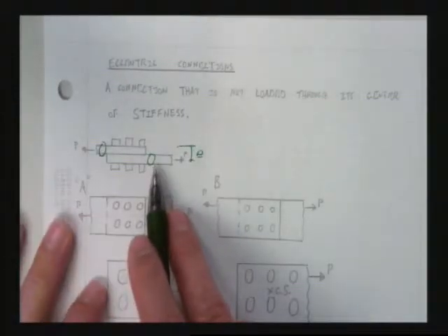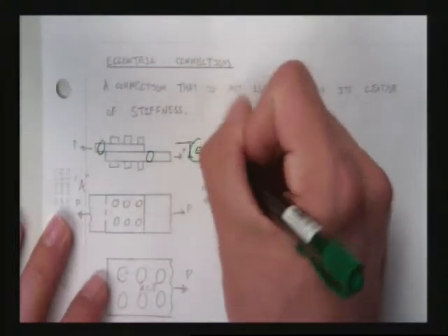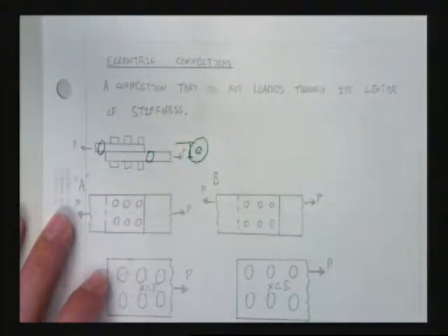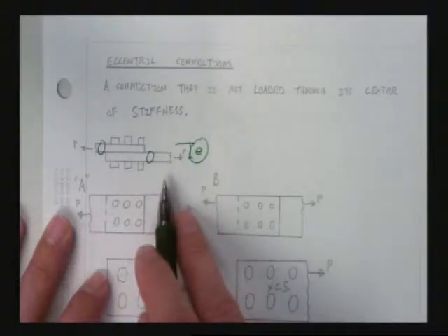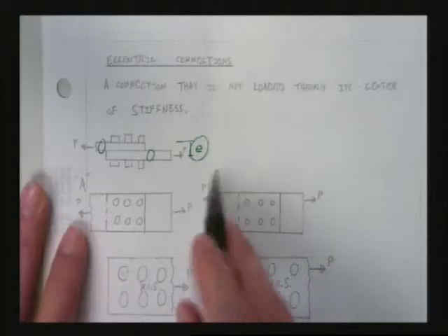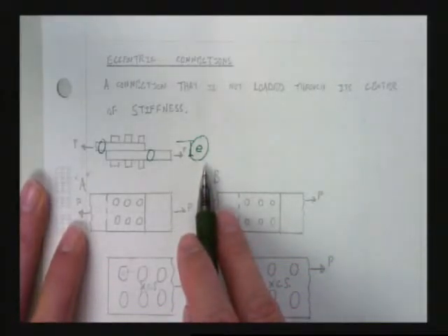The only times I would be concerned about this is if I'm dealing with very thin plates or if my e gets to be very large. Alright? And those are kind of feelings you have to have. It's good to draw things to scale. It's good to look at things in AutoCAD that have been drawn to scale and ask, does that look like there's a big e, a big eccentricity there? And if there is, then you might want to do some of these calculations, all right? But this is not what we're going to be spending the majority of the time on.